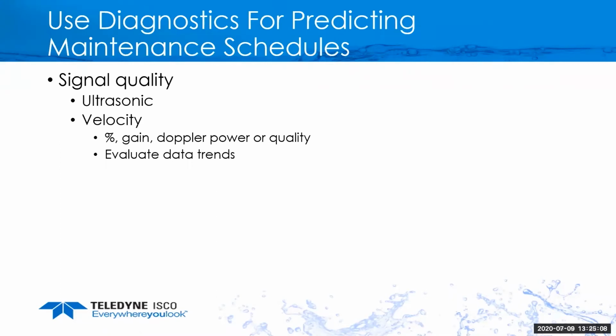What that tells me, though, is that the hydraulics in that channel are very turbulent. So we have very choppy flow. We have waves, and it looked like a lake. It looked like a real rough lake, which means that signal is reflecting off of one of those waves and actually shooting off to the side. So this is a very useful tool to be able to tell you really what's going on.